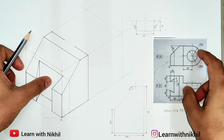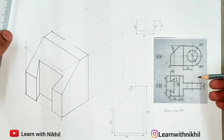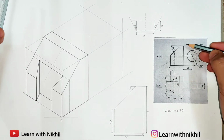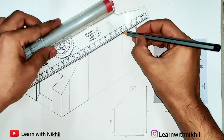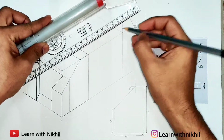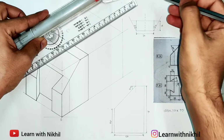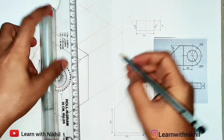Now the back side, as you can see, you have a semicircle from here. Now for drawing the semicircle, you know the procedure. Circle or semicircle, you have to draw a rectangle or a square of sides as a diameter. So the radius given is 35, so the diameter will be 70. So this distance is already 70 millimeter. So we'll draw a rectangle on this plane.